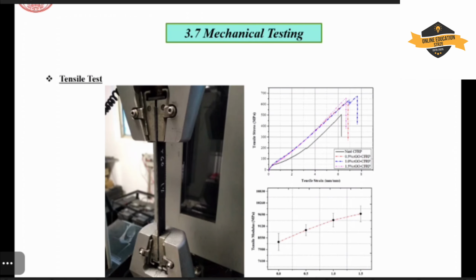And after that, these are the conventional testing processes, in which all types of developed material should be tested through mechanical testing, where the tensile test plays a very important role. We have considered 3 samples, or 3 readings, for each sample, and finally we have taken the average, and that average value is our final value for a single reading. So for a single reading, we have performed 3 repetitions of the test, so that our result has less error.